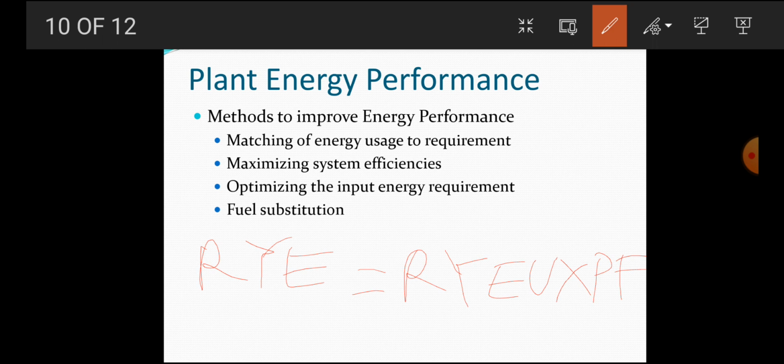Basically, you have seen that we take one year's energy use as a reference, and whichever year is the best for energy use will be considered as the reference. Then if you multiply it with the production factor, that is how much production has increased, so much the energy consumption should increase. So that is the reference year energy.